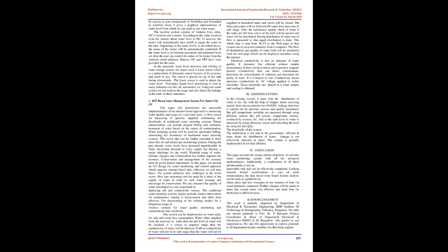The transmitter section consists of an Arduino, HC12 transmitter, laser sensor, and Node MCU. In the automatic water level detection and refilling of water storage system, the sensor used is a laser sensor, which is a replacement for the ultrasonic sensor because of its accuracy and small size. The laser sensor is used to detect the water level.